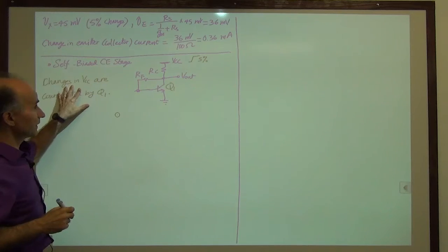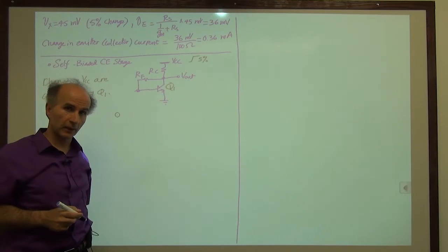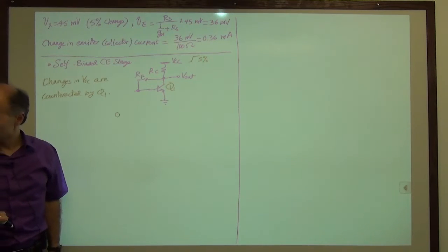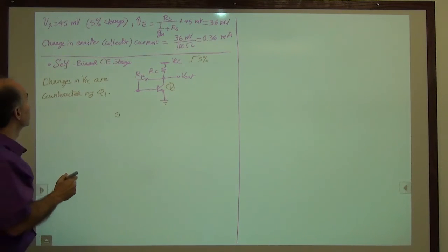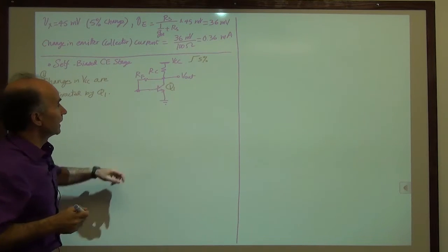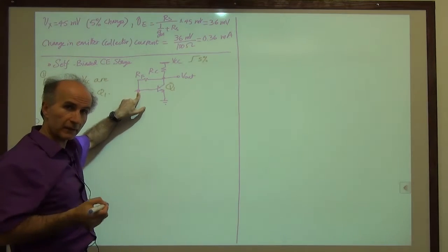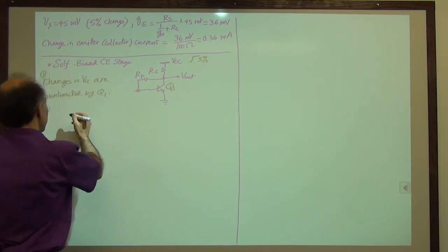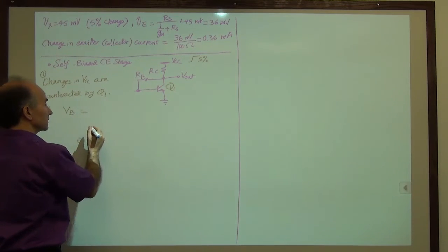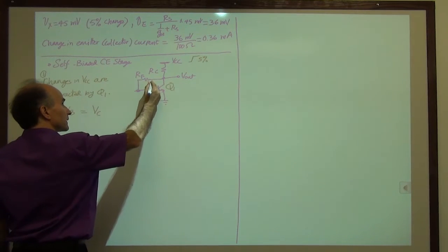All right, so that's an interesting observation. Qualitatively, we feel that this circuit also has a reasonable supply insensitivity. Now, the next observation is the following. So that was one observation. The next observation is also interesting. In this circuit, we can write the base voltage, just DC for bias conditions, and see what we get. We can see that VB, the base voltage, is equal to the collector voltage, this voltage, minus this drop. There's a drop from here to here.